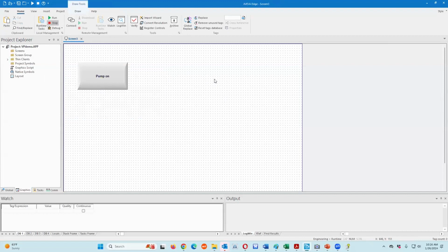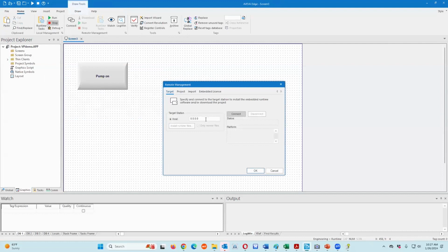Once you do that, the key is to connect to the ViewPAC. You simply navigate to the home screen and click on connect. You have to type in the IP address which you set within the ViewPAC or IWS series. That is done from within the ViewPAC or IWS series. For this one, I have it set up to 99.127.198.234.